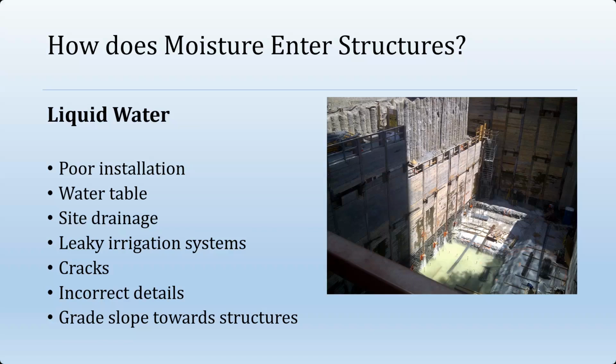So if our geotechnical soils report suggests that our bores find water at, say, 57 feet in one hole, another at 63 feet, another at, say, 75 feet, and the bottom portion of our foundation resides at maybe 21 feet, that's pretty indicative that we have quite low groundwater, and that certainly will help drive the type and choice of foundation protection. Site drainage is also very, very important, and frankly, something I think that tends to ride under the radar.